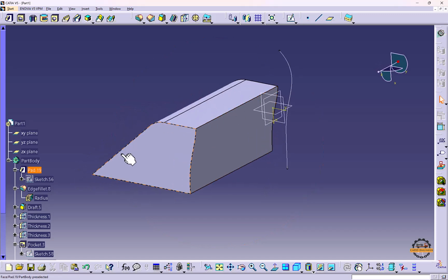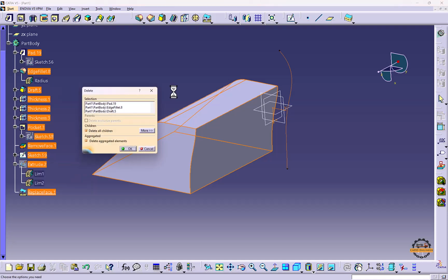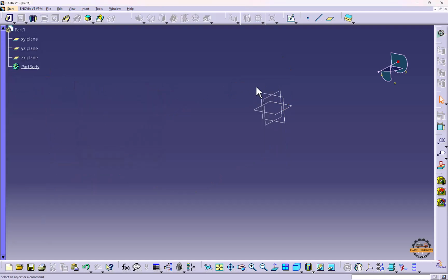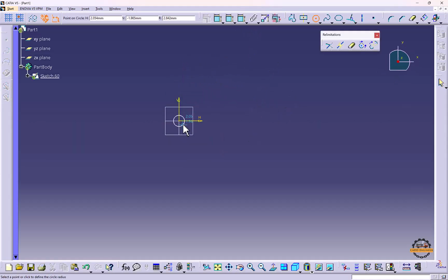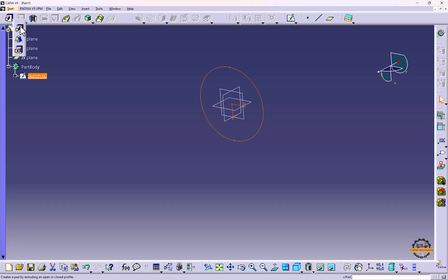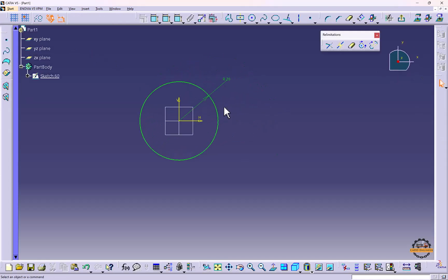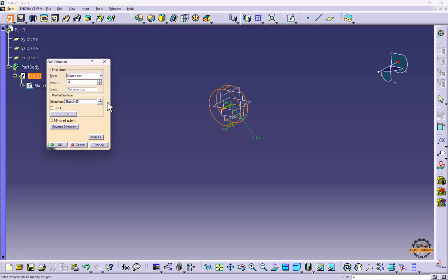Next, we want to add a thread in the shaft case also. The same way we did the hole command, we can do it for the shaft. Let me show you. Let me make a shaft of some diameter. Let's specify the diameter to be 20, and we'll make an extrude of this. I'll make 10 radius, it's 20 diameter. So we'll make a pad of this at some depth. Let me take 45 or 40, or let me take 60.